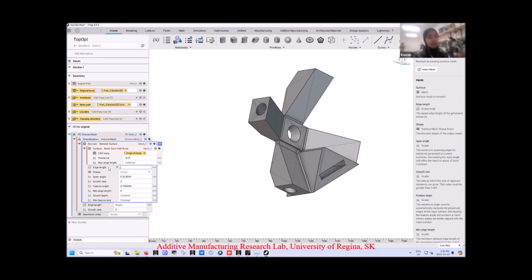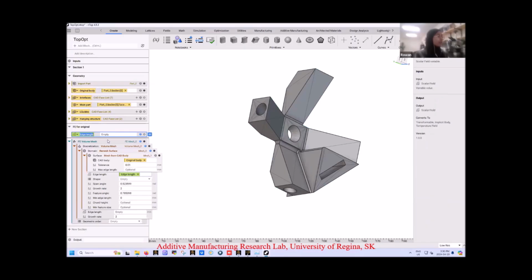as the edge length will be an input for several parts later on, it's a good idea to make it a variable outside. So in this case, you'll specify the edge length only once, and if you have any changes in your design later on, you can just change the edge length in this block, and it will automatically be changed in all the other blocks where this edge length is an input. And for this situation, I'll write, for example, 2 as an edge length.